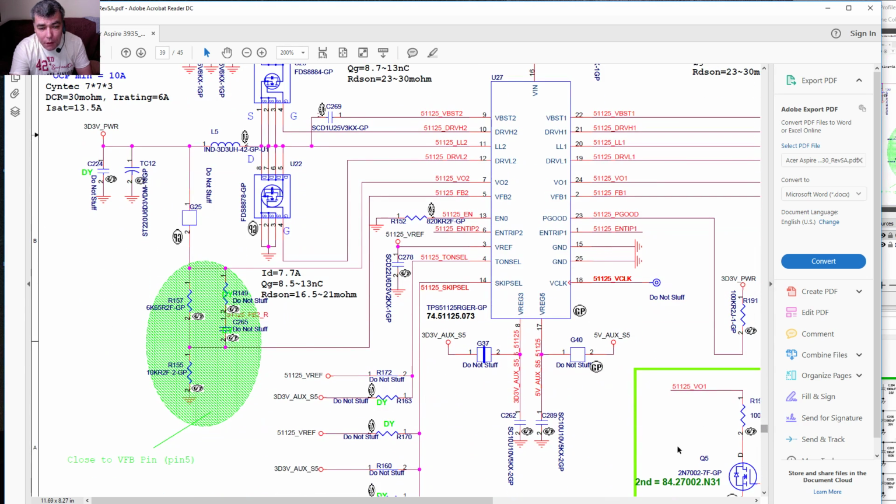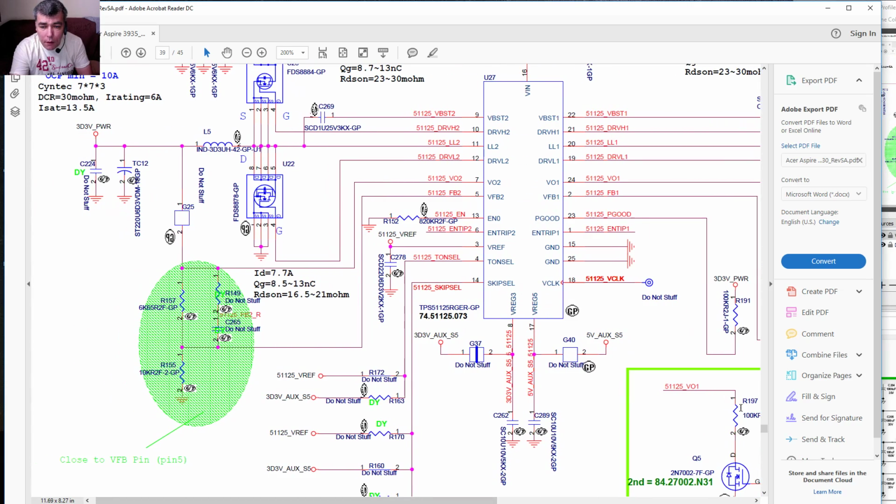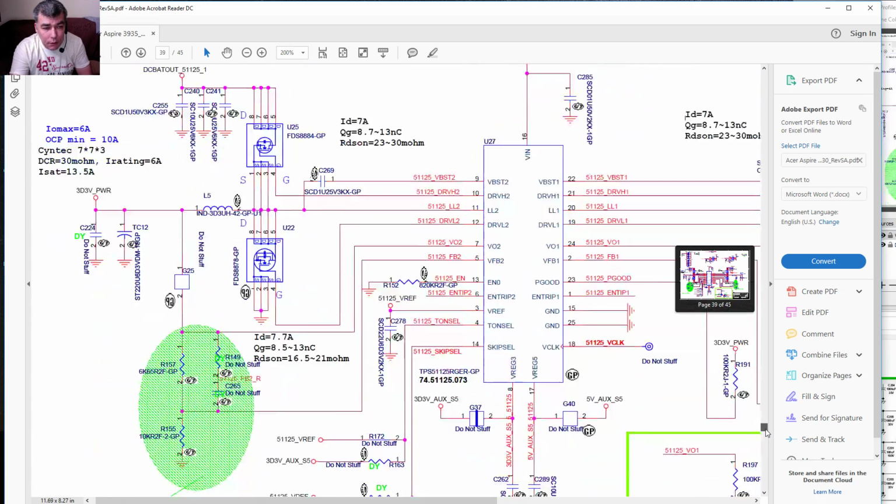That's what we spoke about. If you didn't see the last video, just check the last video with the motherboards. This is the path to find the power supply on the motherboard, yeah? 2 Mosfets, the coil, the ceramic capacitors, and the big output capacitor.